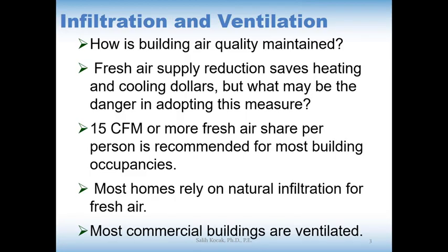And here, most homes, the residential constructions, rely on natural infiltration for fresh air, because we have cracks or openings under doors near windows, and some heat losses when you open the doors and so on. So that's why most homes rely on natural infiltration, so no need for ventilation most of the time. However, in sealed tight commercial buildings, ventilation is important to provide the fresh air.